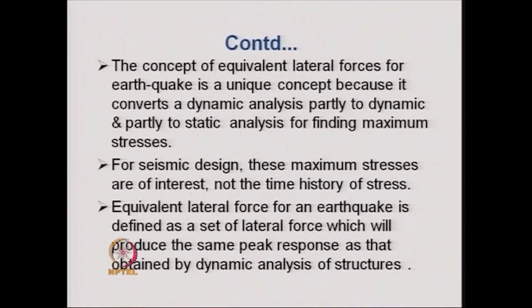because we construct a set of equivalent static lateral loads in each mode of vibration, and this set of lateral loads, when applied to the structure, provides a response of the structure. That response happens to be equal to the maximum dynamic response that the structure would have undergone if it were vibrating only in that mode.